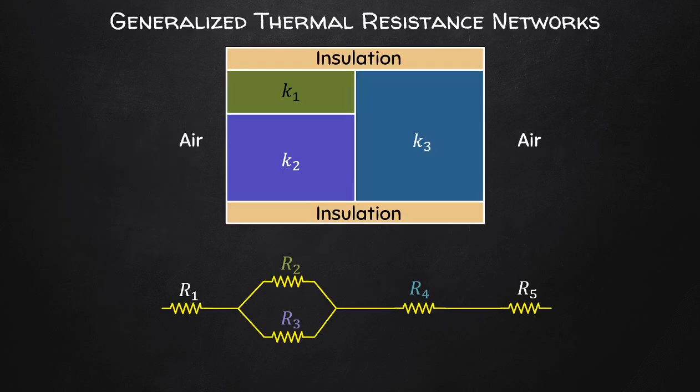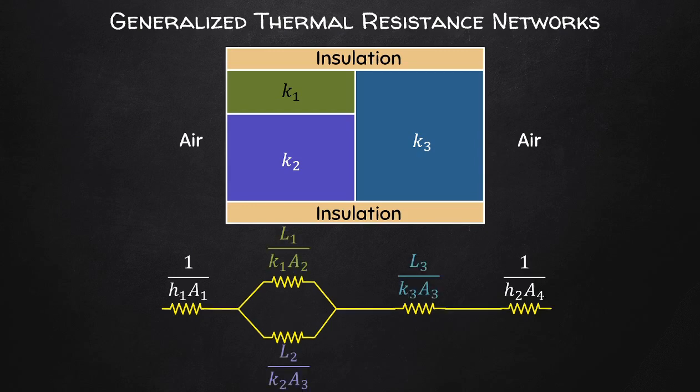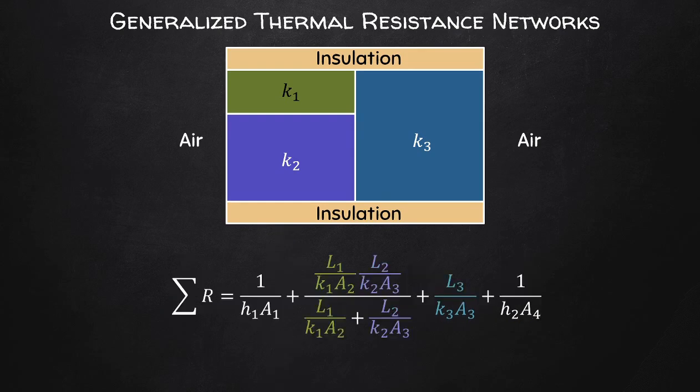Just before we get to finned surfaces, let's also quickly recap the last few concepts that pertain to resistance to heat transfer. If we have resistances in parallel, for example, as shown here, we define the resistances mathematically, and those resistances that are in parallel can typically be approximated in the same way that we do so for electric resistances that are in parallel.